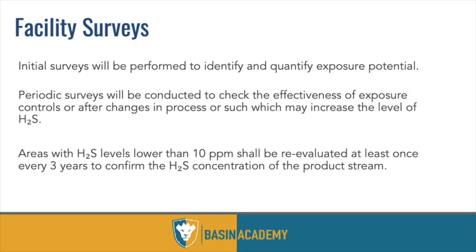But then once you see a breathing air system or a windsock that's red and white, then typically we know that there's H2S, and when there's a red and white windsock, it's over 100 parts. Not every company does that, but if you see that, then that's what that means.